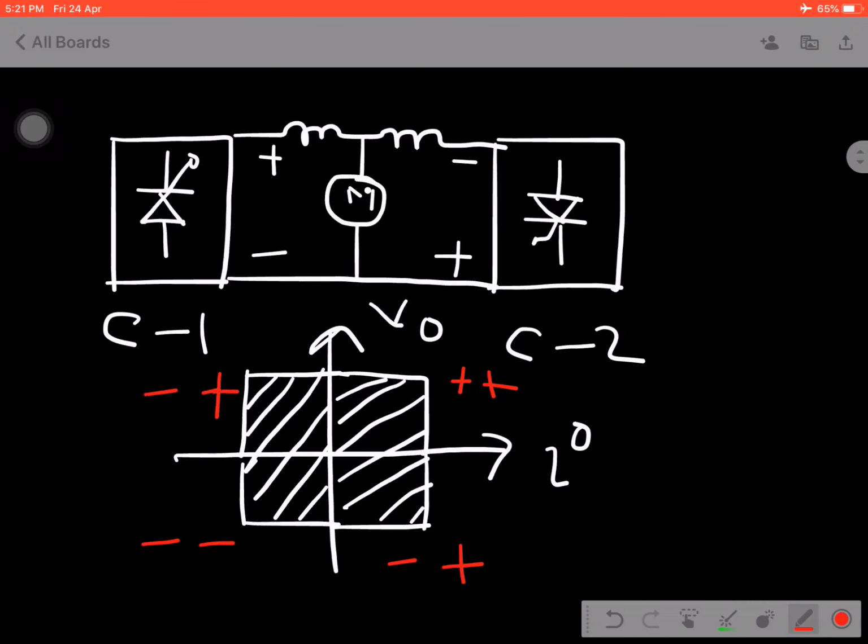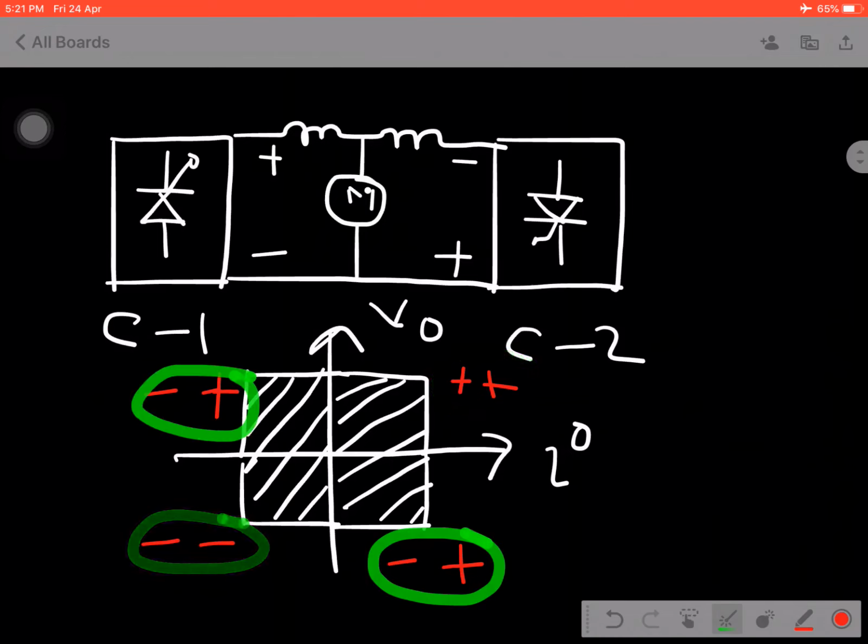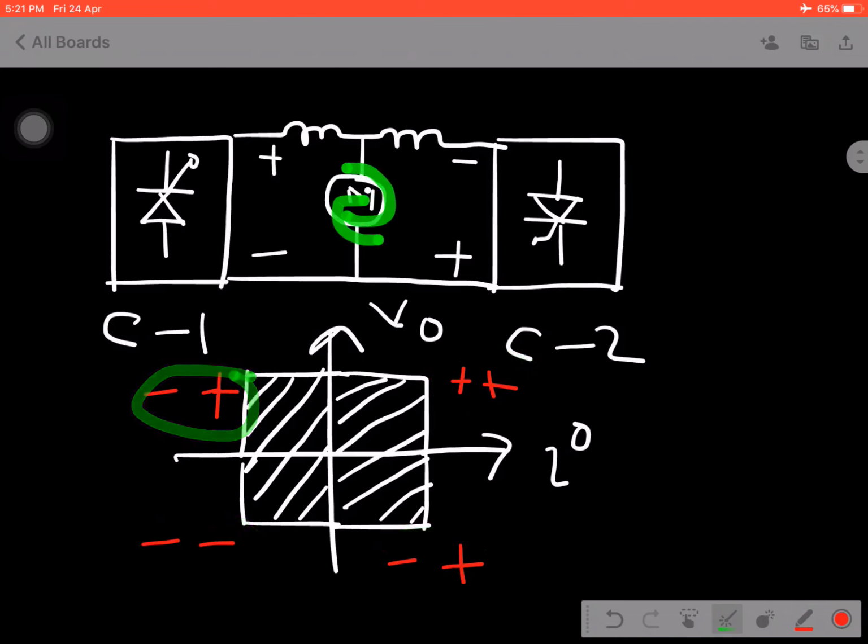That means we can say they are operating in opposite directions for the two converters. That is why the machine starts working in the clockwise or anti-clockwise direction. This is the application. So we can control the speed of the machine, or the direction. It can be easily applicable for the hoist mechanism, or for the lift mechanism, where the machine works in both directions, clockwise and anti-clockwise. Okay, so this is the application part.